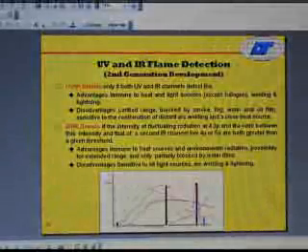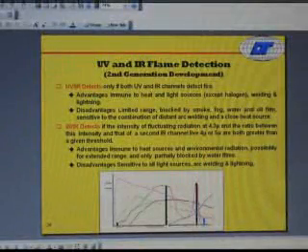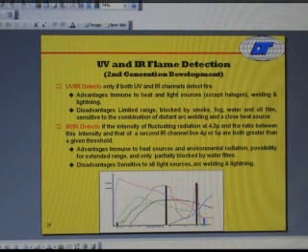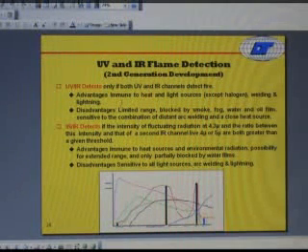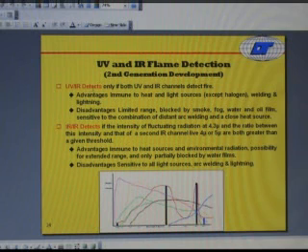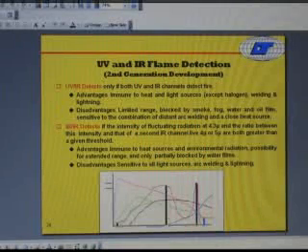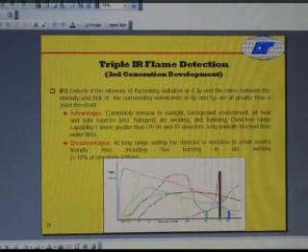And this is UV-IR. It tells you UV-IR detectors only trigger if both UV and IR channels detect fire. Advantages are immune to heat and light sources, but especially if there's welding, you don't want to use that. We don't use UV-IR anymore. Basically, an IR detector is a better way of going about it. And the best one that we use lately is triple IR.